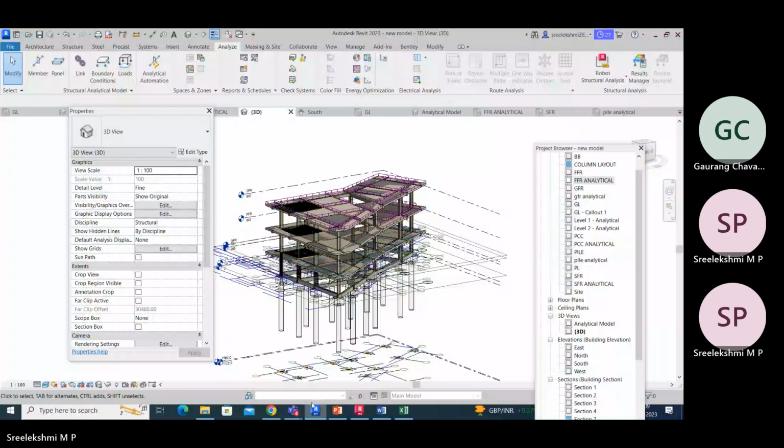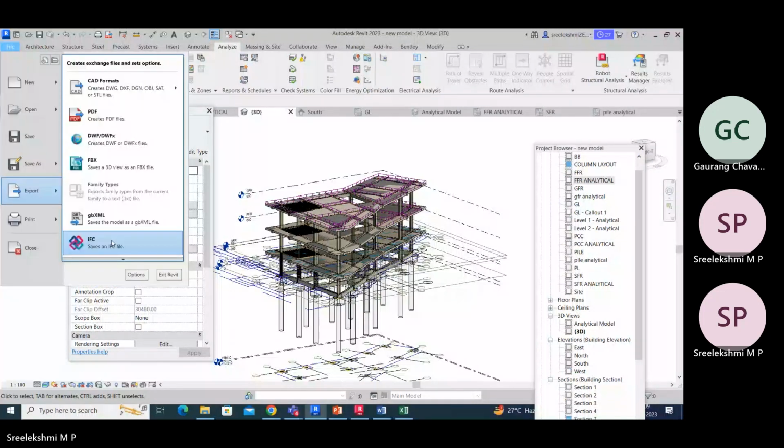Okay, then if we take any 2D drafting view here, we can convert it into DWG, DXF, or DGN formats. All of these are supported in AutoCAD. Also, in Revit we can import AutoCAD files, but we can't work with them the same way we do in AutoCAD.